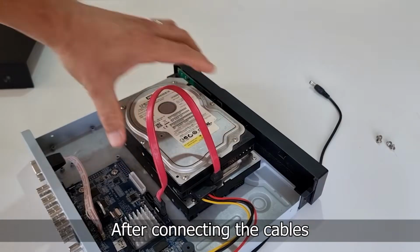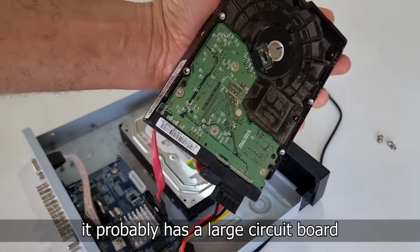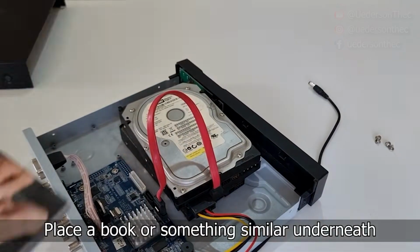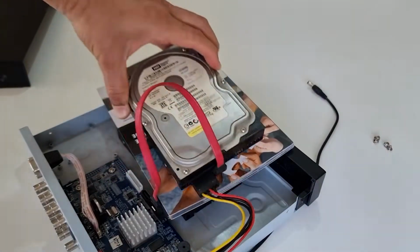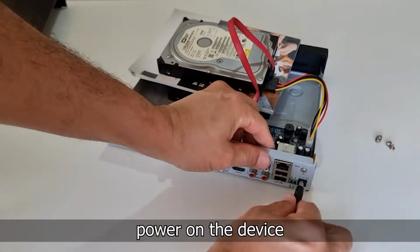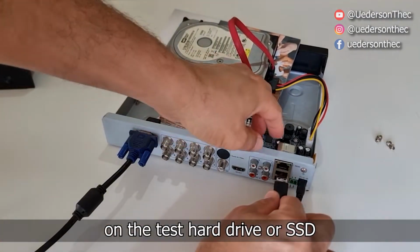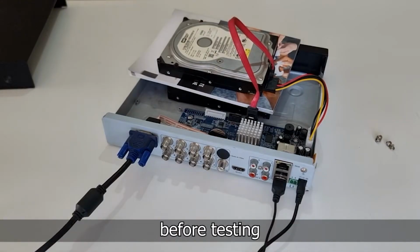After connecting the cables, if you're testing a 3.5-inch hard drive, it probably has a large circuit board. Place a book or something similar underneath to keep it from touching metal parts and avoid damaging the drive. After connecting the test drive, power on the device. At this point, it's important to mention that this procedure may erase everything on the test hard drive or SSD. Make sure there's no important data on it before testing.